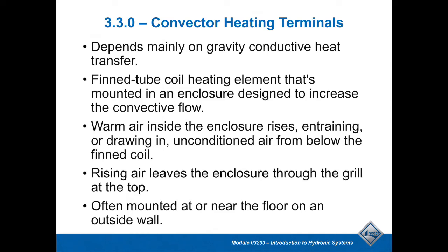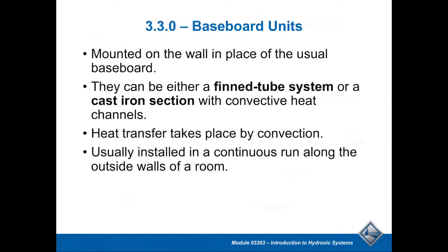They'll have a fin tube coil in an enclosure that's usually recessed in a wall, but it doesn't have to be. Those are typical ways they'll run that. It's a very simple system. You can put a valve in there, which typically would be controlled by some thermostat. Not probably your highest-end type of heat emitter, but very effective. A lot of these convectors are put in vestibules, but I've seen them in regular rooms and hallways as well. They'll be totally fine. Near outside walls would typically be ideal.